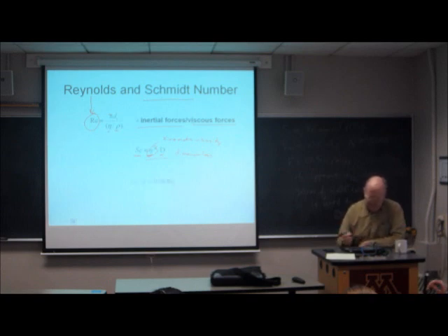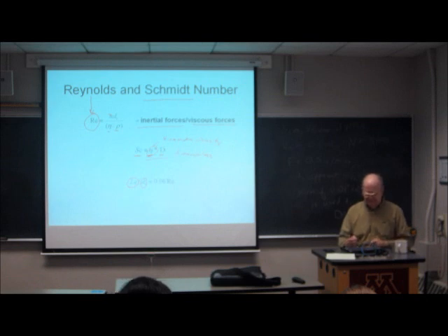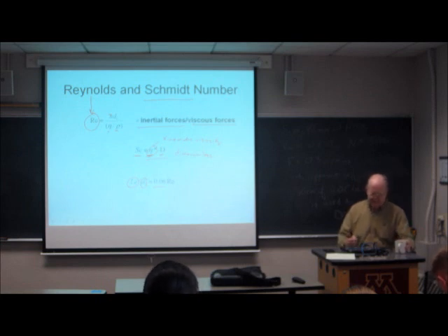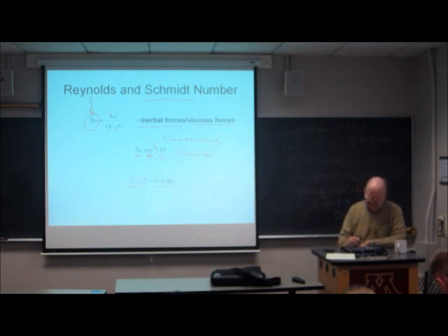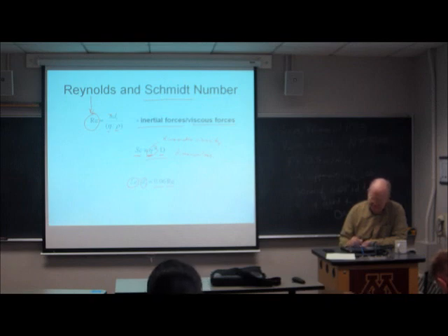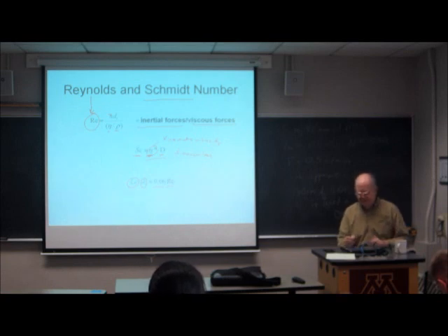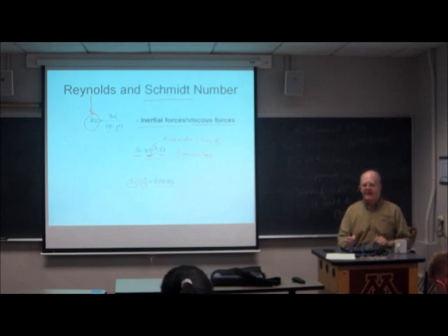Okay, one of the reasons for telling you about the Reynolds number right now is that this is the entrance length and this is the diameter of the tube. And the entrance length is going to be equal to about 0.06 times the Reynolds number. As we'll see, Reynolds numbers seldom, if ever, get above 10. So the ratio of the entrance length to the diameter of the tube is about, let's say, 0.06 times 10, call it 1 tube diameter.